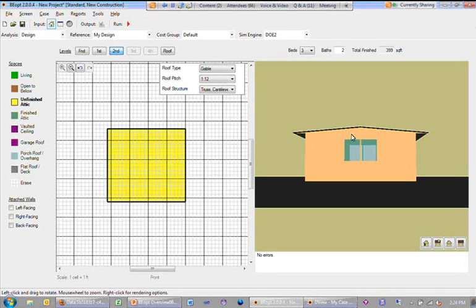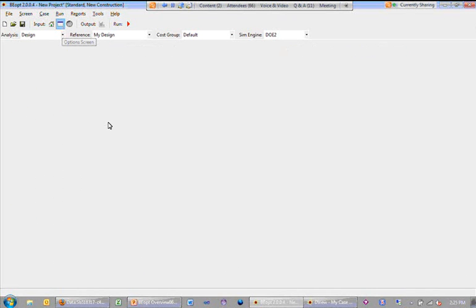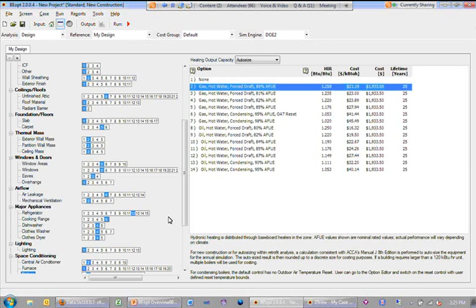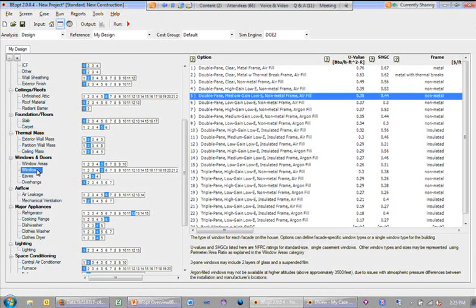Can you speak briefly about changing the window characteristics? I understand if you have 20% on each side of the house or 30% on certain sides, whatever. But if I have some windows that are going to be double pane, some are single pane, some are wood, whatever, in retrofit application, creating my existing case, am I going to have to do off spreadsheet U calculations of coming up with the averages of all the different directions and then working through it, much like we just talked about the roof insulation?